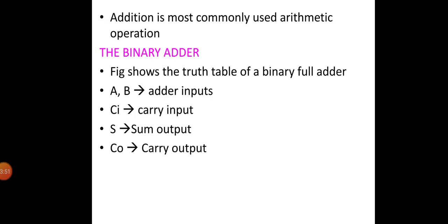Typical logic level optimizations try to rearrange the Boolean equations so that a faster or smaller circuit is obtained. An example of such a logical optimization is the carry look-ahead adder, and circuit optimizations, on the other hand, manipulate transistor sizes and the circuit topology to optimize the speed. And before considering both optimization processes, we will take a short look at a summary of adder circuits. Now first let us look into the binary adder.